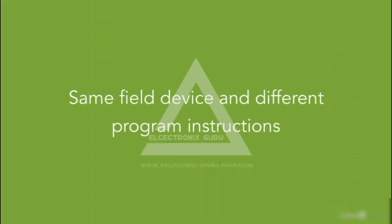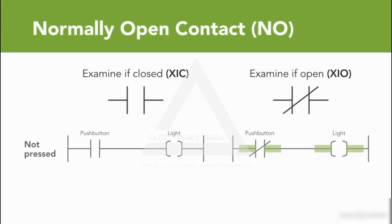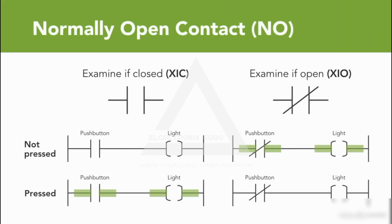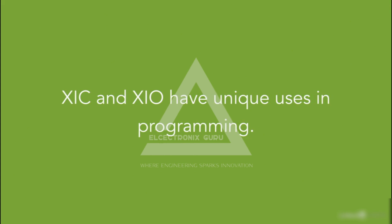So as you can see, although we're using the same physical device, which is a normally open contact, the way we program it in the software using ladder logic produces a different output. This is to demonstrate the difference between using an XIC and XIO while having the same normally open contact, the same physical device. XIC and XIO have their uses in programming. Each is used for certain tasks, like emergency stop, for example, as you will see later in the course.